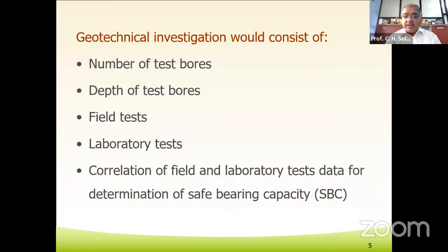What would a geotechnical investigation consist of? Here I have pointed out something. How to decide the number of test bores, how to decide the depth of exploration of the test bores, what are the field tests to be conducted in general, what are the laboratory tests to be conducted, and correlations of the field and laboratory test data for determination of the safe bearing capacity.